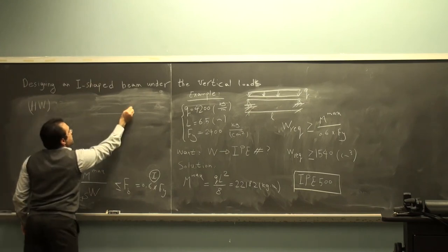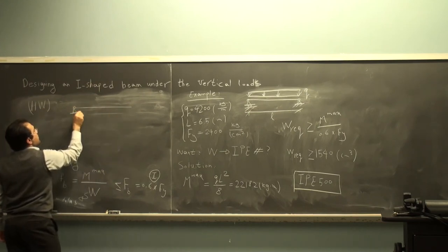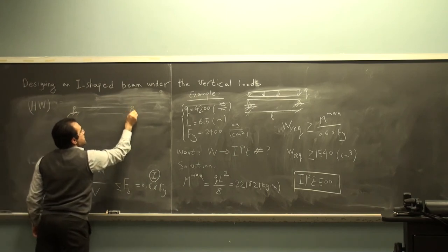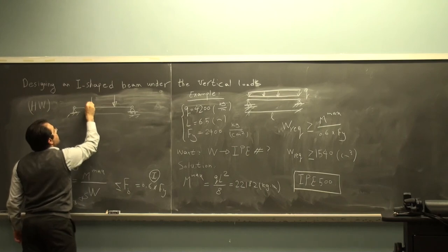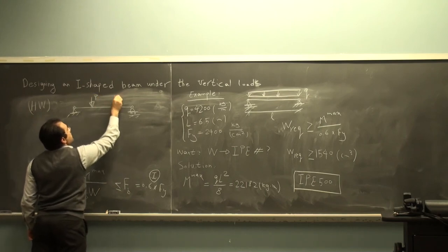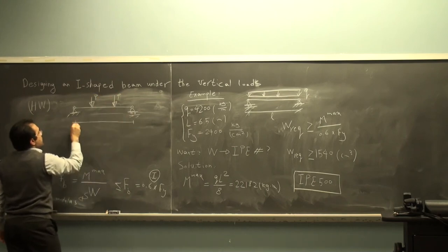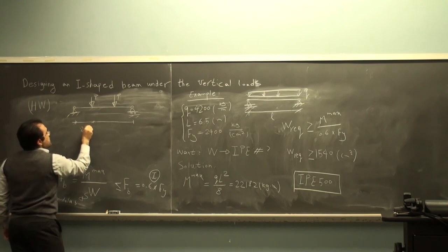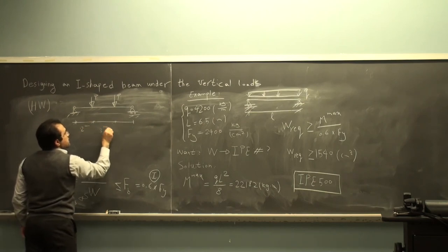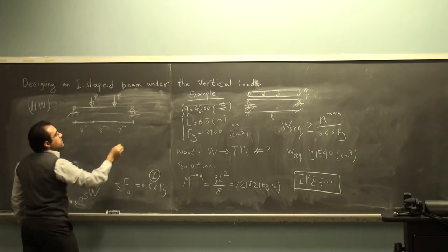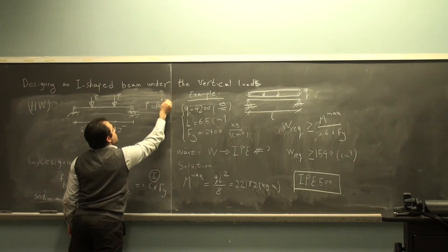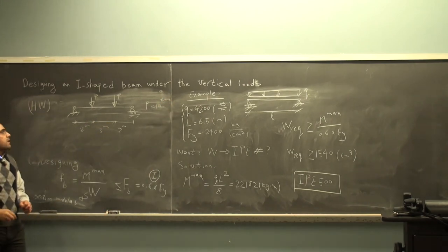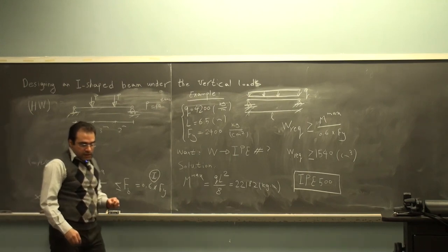say we have a beam like this, the same boundary conditions, but this time we have 2-point loads like this. They have the same magnitude, and this is 2 meters. In the center we have 3 meters, and at the end we have 2 more meters. And P is 10 tons. So I want you to design this beam and hand in your solution for next session.